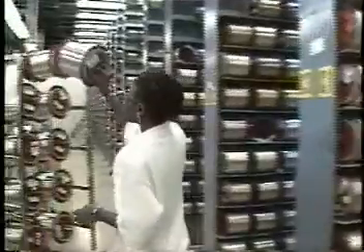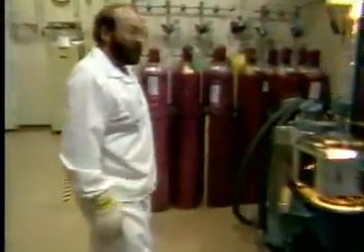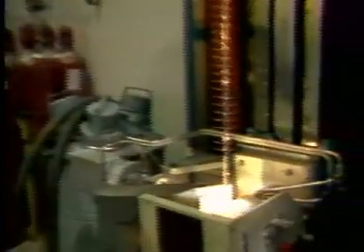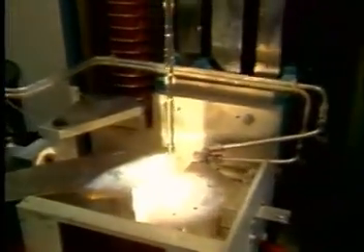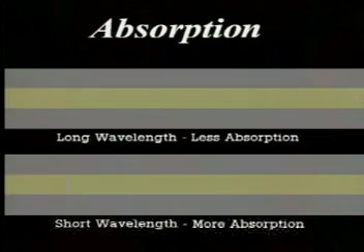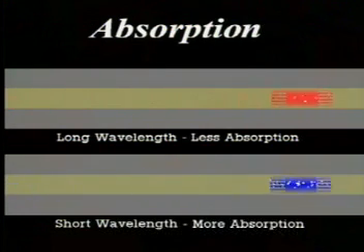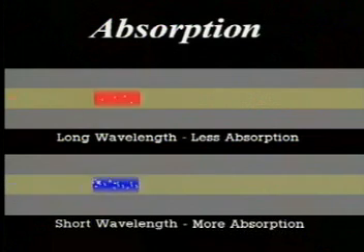Among the intrinsic losses present in optical fiber are absorption and scattering. Absorption is caused by impurities, such as metal ions and hydroxyl ions, introduced in the manufacturing process. The impurities absorb portions of light energy and re-emit it as minute quantities of heat. Absorption losses in fiber are highly wavelength dependent. Shorter wavelengths tend to be absorbed more easily by impurities in the glass.